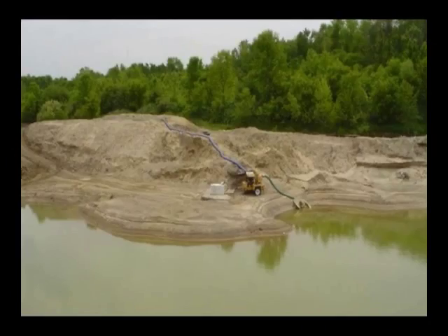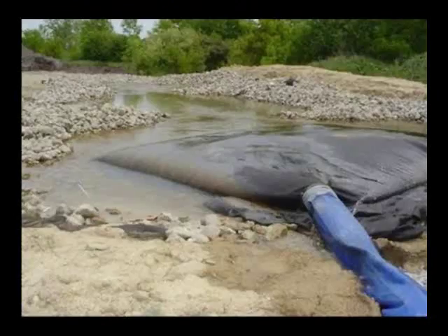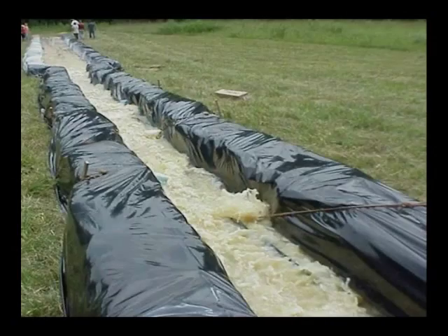The water that is removed from such an area must be discharged to a stabilized area at a non-erosive velocity. If the water is laden with sediment, measures must be taken to remove the sediment prior to its reaching a water body or storm inlet. Sediment-laden water may be pumped through geotextile filter bags into sediment basins or through filter berms constructed of stone. If the suspended sediments are clays or fine silts, it may be necessary to introduce PAMs into the discharged water to facilitate filtration or settling.